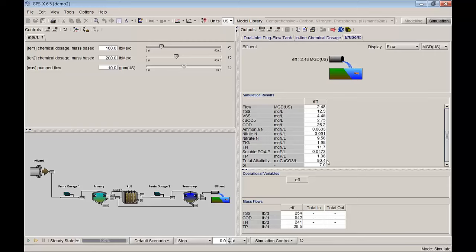You can do those optimizations manually yourself by investigating the performance of the plant. I will mention at this point, too, that, of course, you can overdose your phosphorus removal, and that will be reflected in the biological activity in the plant. So all of our biomass growth equations do show that phosphorus is required as a nutrient, and there's a half saturation coefficient that controls how sensitive the biomass is to the presence of phosphorus.